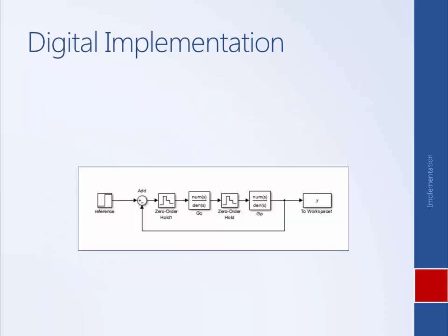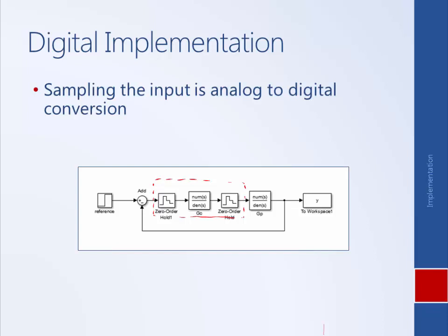So here's a picture that's sort of representing a digital implementation of a control algorithm. We have the continuous world. Here's our plant, but the controller is implemented on a computer, for example, in this dash box. And so the input to the controller must be sampled. This program that's running that represents our control algorithm, it runs periodically and it takes some time. It's scheduled and it needs to run in concert with other algorithms.